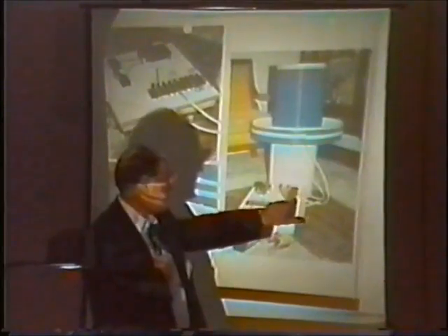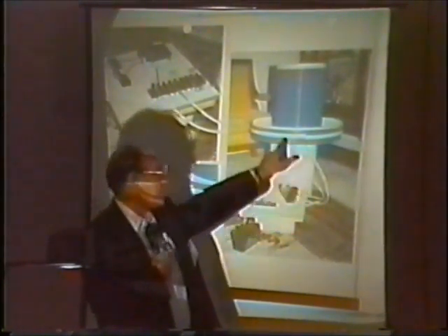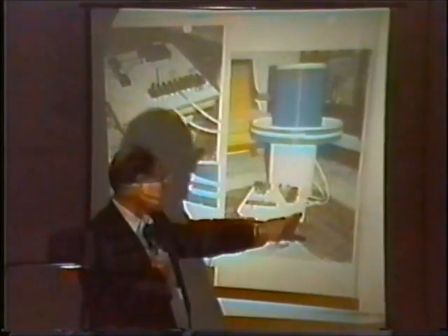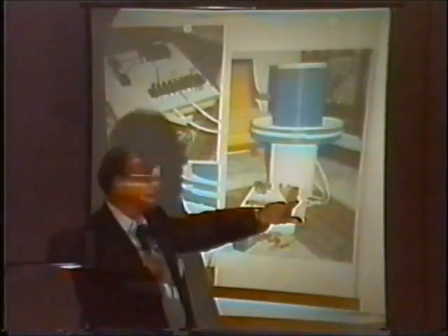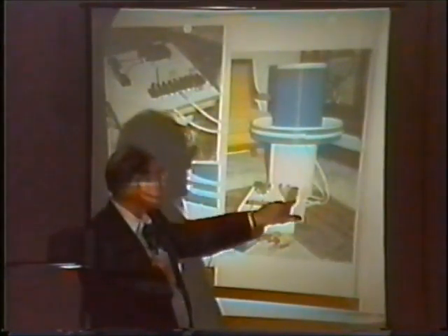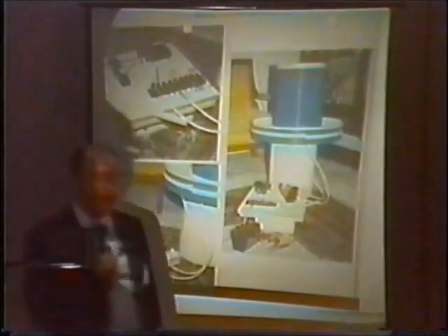The blue one here is the negative lead coming back from the L2 coil. The one that's white here is your positive lead going out. So between those two, you've got this 10,000 volt reconstituted mica capacitor.